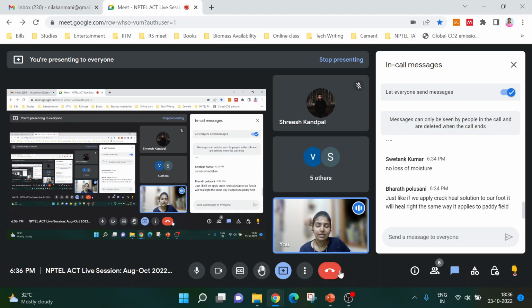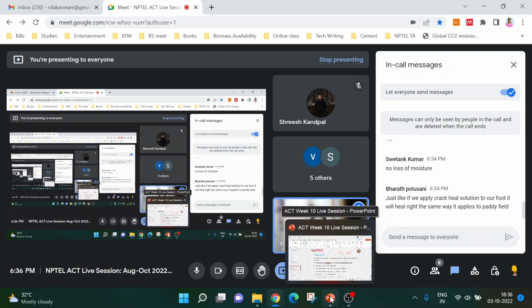So here, when soils are in different layers, they will be restrained when the top layer shrinks, because loss of moisture will happen only from the top soil layer. If you check the soil beneath 1 feet, you can find some moisture. So there is some reduction in volume from the top layer, but the bottom will not shrink. So there is a restraint between the layers.